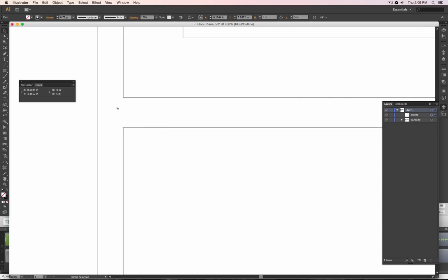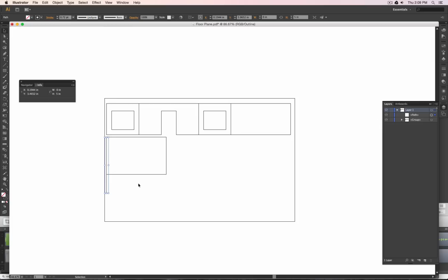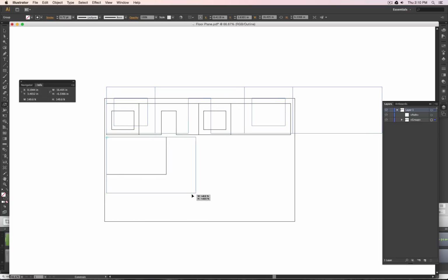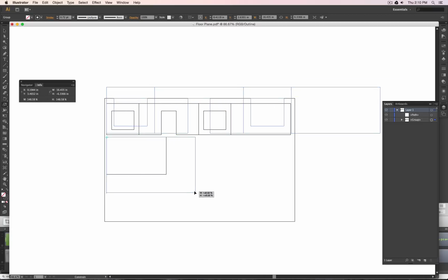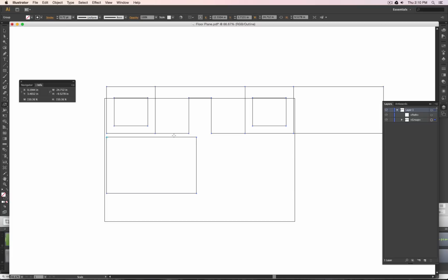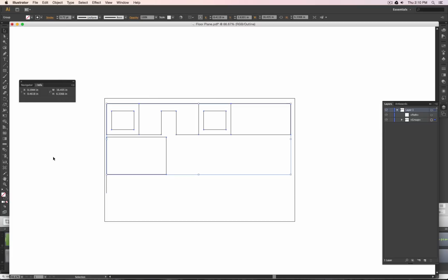In case you don't see anything snapping, press Apple U or Ctrl U. And the main reason for that is now I can select this whole object there and press S for scale, move this one to there, and then scale till, here you see it hits, and you see I'm pressing and holding shift, so I scale at the same time. There.